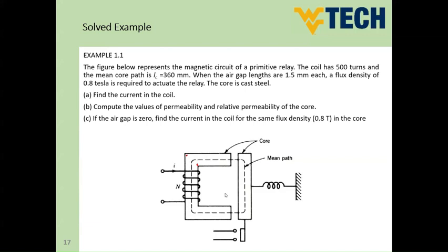Also, as you can see, the left side is connected to a supply of electricity with this number of turns. Once we supply this with a certain electric current, a flux will start moving, and you know that flux prefers to move in magnetic material because it has lower reluctance compared to the air. So flux will start moving here inside.